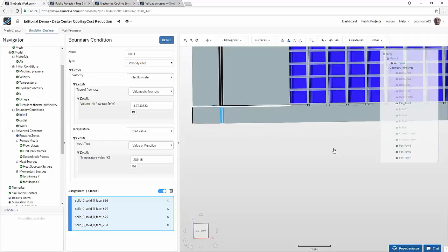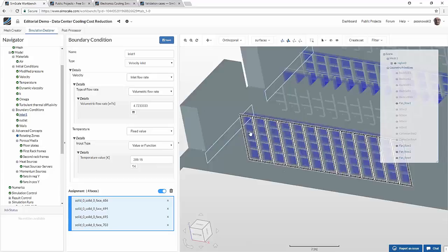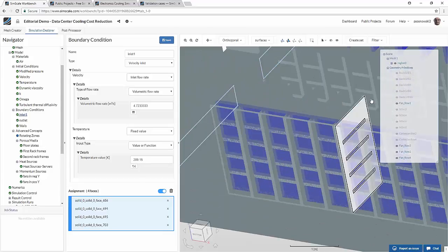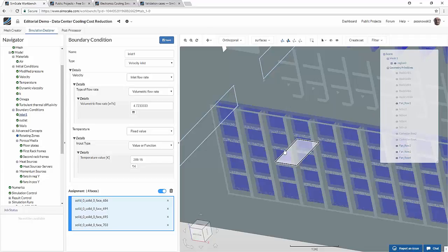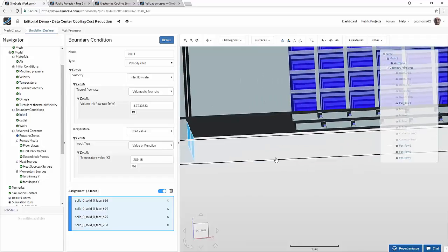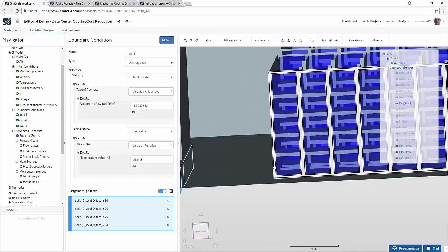You can either use the approach that we have in this case, where we introduced a virtual box that represents the presence of the fan itself, and then we add a so-called momentum source. But you can also upload the geometry that will represent the fan itself. You can even have multi-reference frames, so MRF modeling of the flow that is being generated.